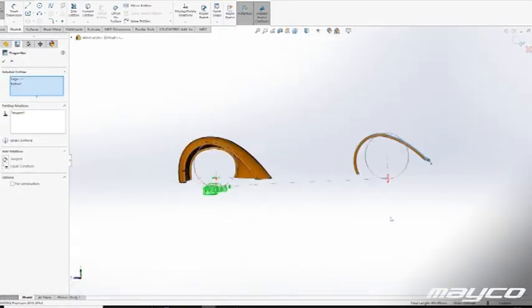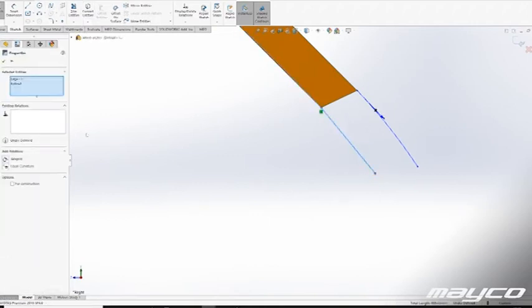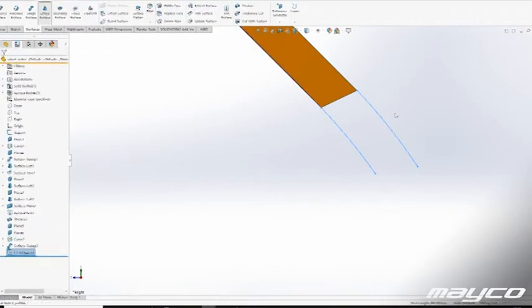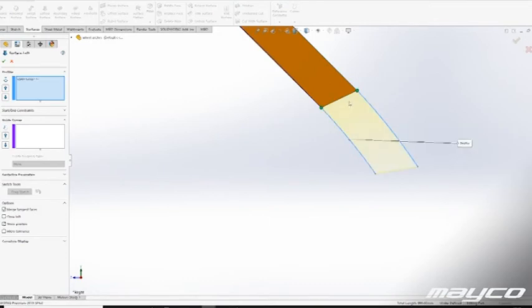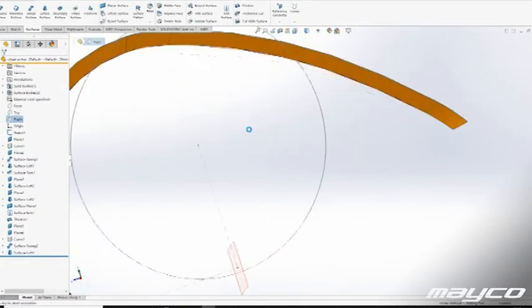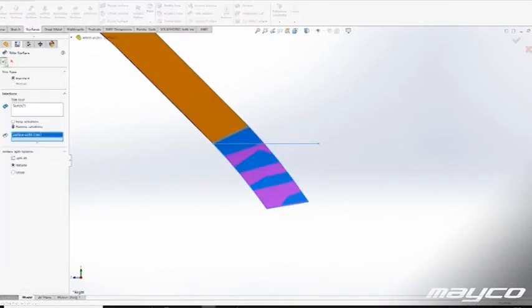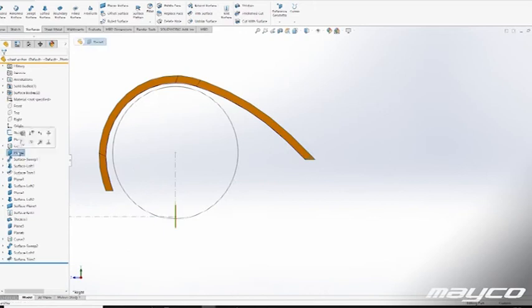Very often, however, you'll get a very big spike in the surface where it either dips down or dips up, and then you need to fiddle around with how the surface connects to other surfaces, if it's tangent, for example, and it's just trying.